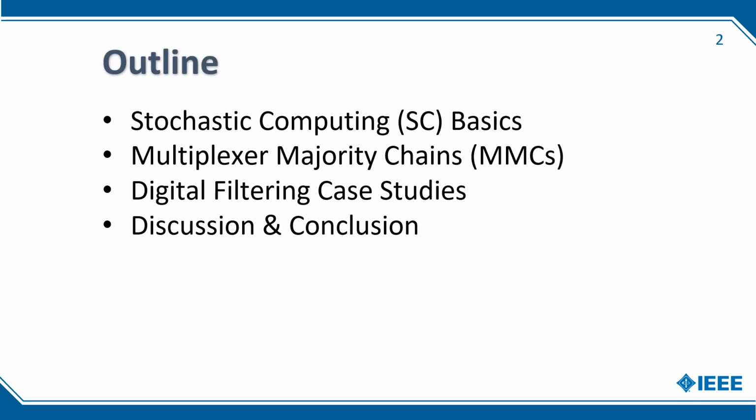For this talk, we'll begin by outlining some of the background from existing stochastic computing research. Our paper is primarily focused on the design of probability conversion circuits, or PCCs, which are a core component of stochastic number generators, or SNGs. We will see how two of the most common PCC types, comparators and weighted binary generators, are at opposite ends of an area and accuracy design trade-off.